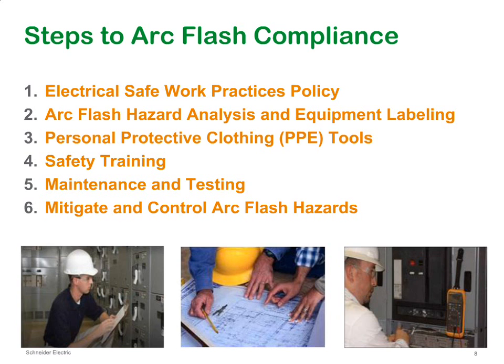What's going to happen is, if an arc flash occurs somewhere in the power system and the circuit breaker feeding that circuit is not properly set, adjusted or maintained, there's a possibility that the breaker will not trip, or not trip within the time frame that it needs to, and that malfunctioning of the circuit breaker could significantly increase the amount of energy downstream. In other words, the worker could go to the equipment, read a certain amount of energy on the label, try to protect himself with the appropriate clothing, and then find out, if an event occurs, that he's subjected to significantly more energy. And that is not a good condition. So that could happen if equipment is not properly maintained.